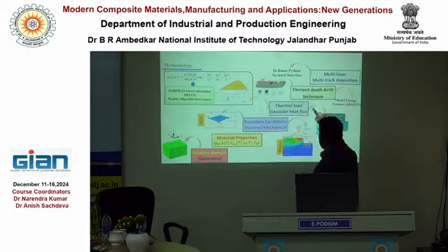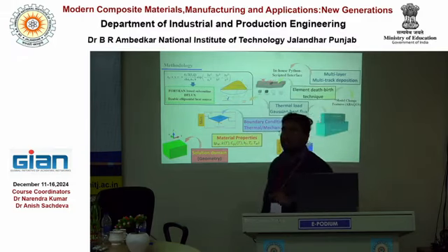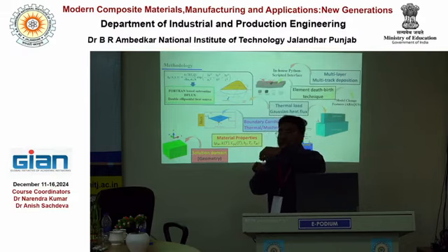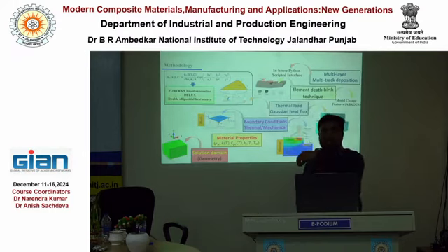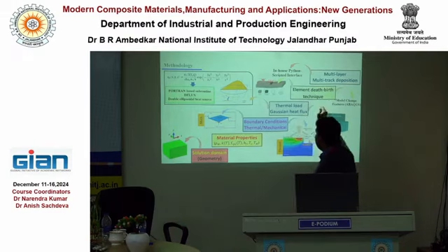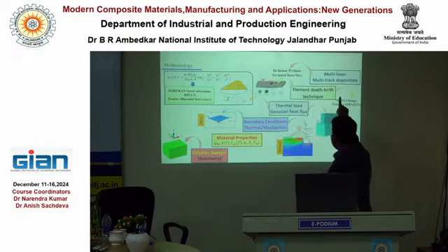Thereafter, since we are dealing with additive manufacturing, element death and birth is most important, because at the position where we are giving the heat source, at that position only material is depositing. It means that wherever heat flux will be there, element activation will be there at that position only. So we have also taken care of the element death and birth analysis, meaning the position where we give the laser source, there only the material deposition will happen.